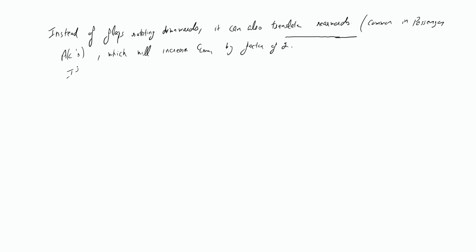If we use slats at the leading edge, or slots in the surface, then CL max can be increased by a factor of even 3.